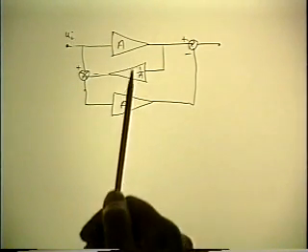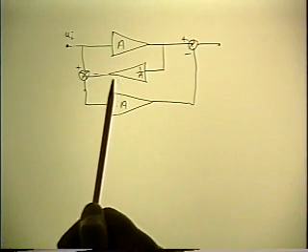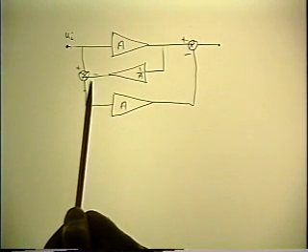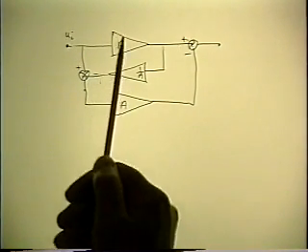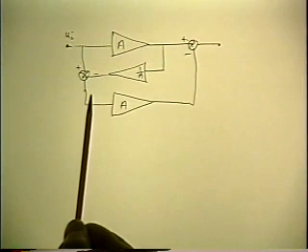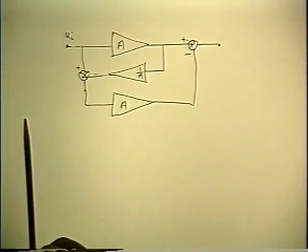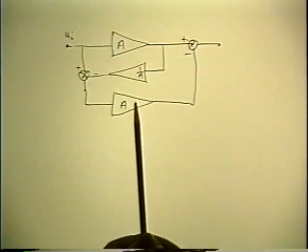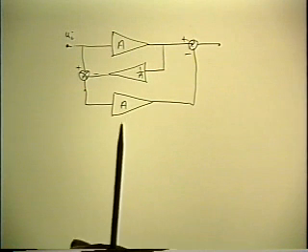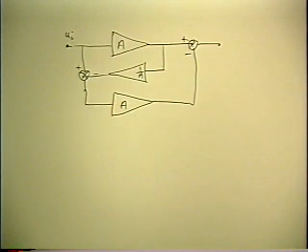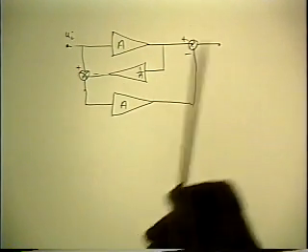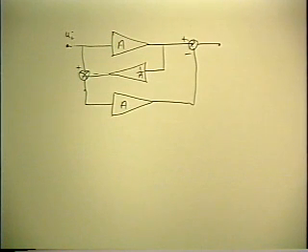Because what had happened was that the principle of his distortion cancellation was the subtraction of two equal quantities to give 0. Trouble is, you don't get 0 because you can't maintain the tracking. Because of the gain variation, the matching of the paths is not maintained. And it doesn't take much offset to get the distortion almost back up to where it was to begin with. It's the small difference of large numbers problem. Again, not once but twice in the same system. He's trying to do 2 subtractions. No wonder it didn't stay put very long.